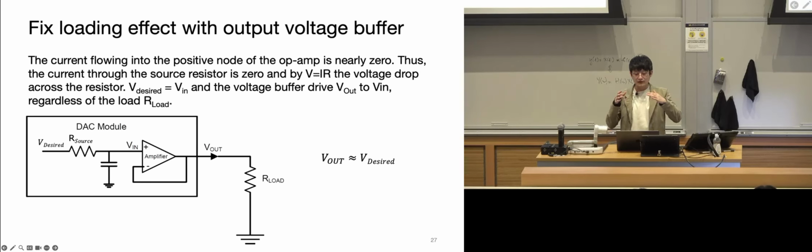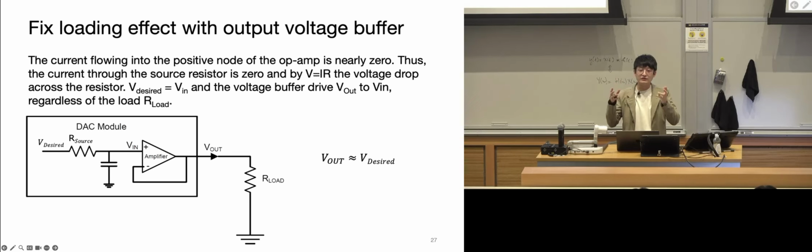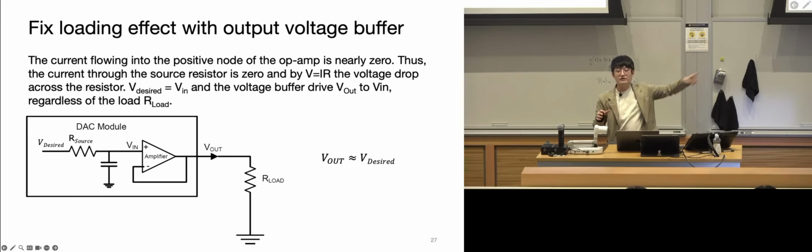So you will see on either ADCs or DACs the operating range of that. That typically means if the output load that's been connected is larger or smaller than that amount, whatever circuit they have inside will not operate correctly. So even if you add this voltage follower, it doesn't solve the problem. It just gives you a relatively consistent output within a designed range of that hardware component. It doesn't solve everything. Any other questions regarding this?